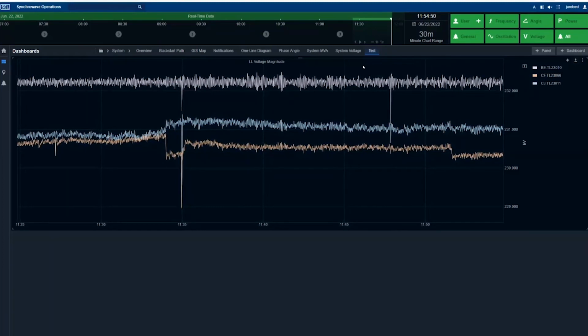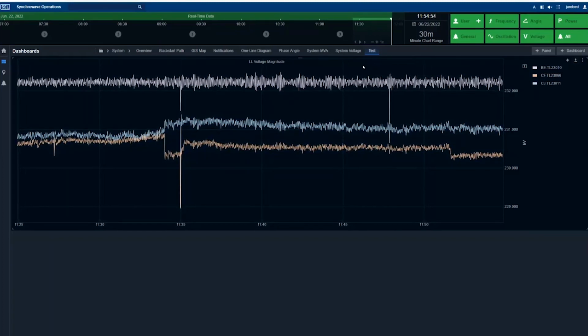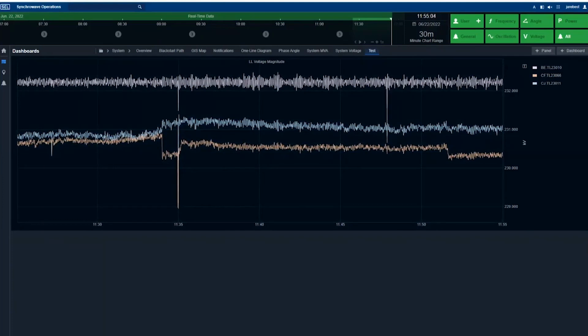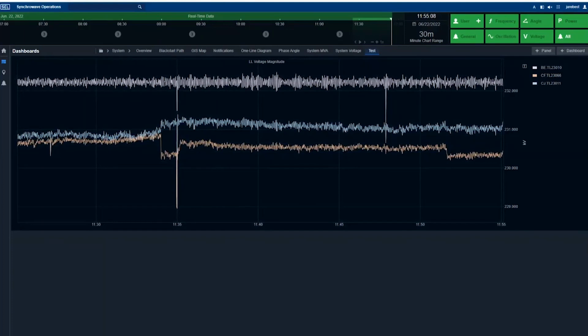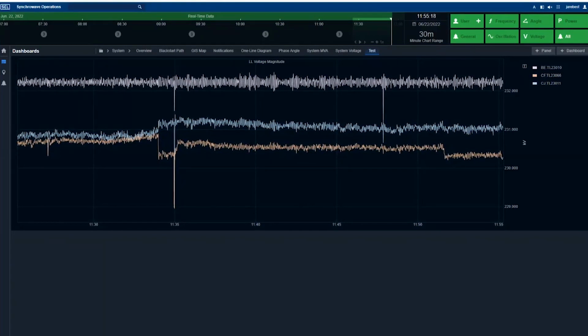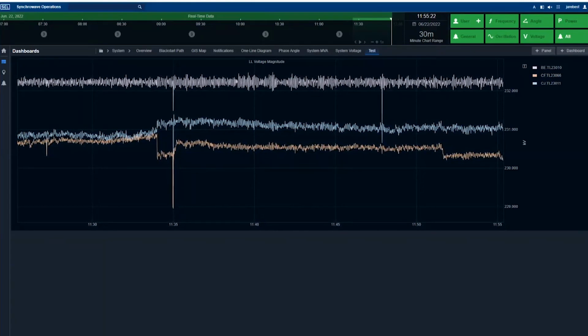Okay, I got one here that I'll answer quickly, Jared. The question is, would it make sense to include another VT in that station at the same voltage for comparison purposes and include that in the analysis? So this is back to the instrument transformer failure. And yeah, that's a great thought. I think it's more appropriate for that to be done just at the substation level because those measurements are right there. And in fact, the SEL RTAC is working on a solution that does that, and also takes in bus configuration and other details to make it work really well.